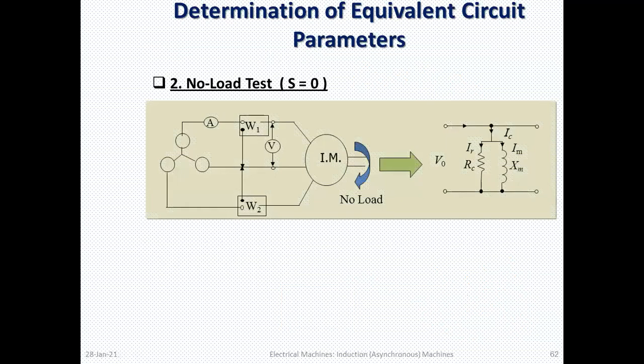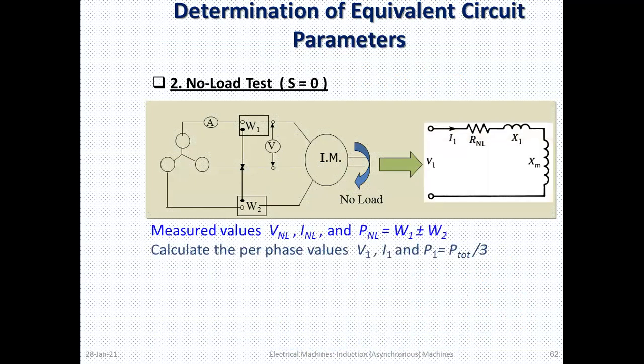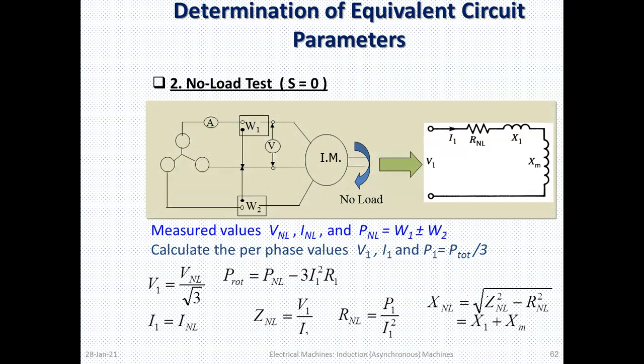Now, determination of equivalent circuit parameters. We have to perform two tests here. The first is called the no load test. No load test means our machine runs without load. Here I am showing some diagrams.